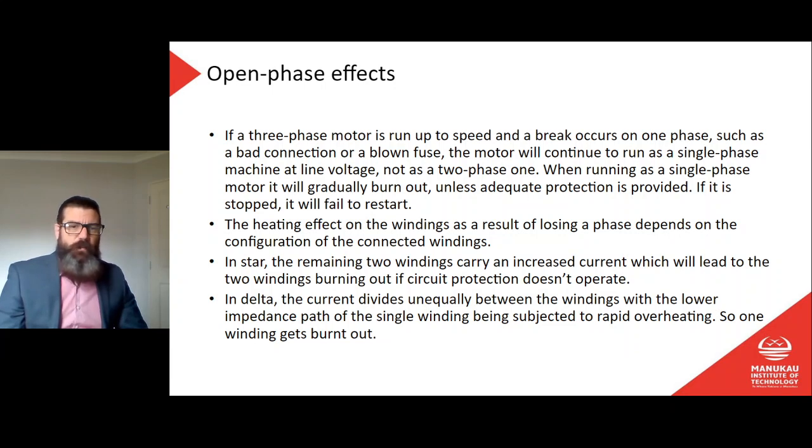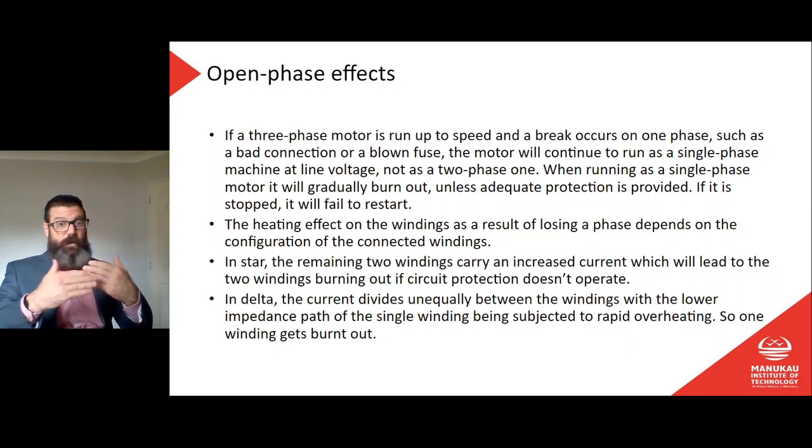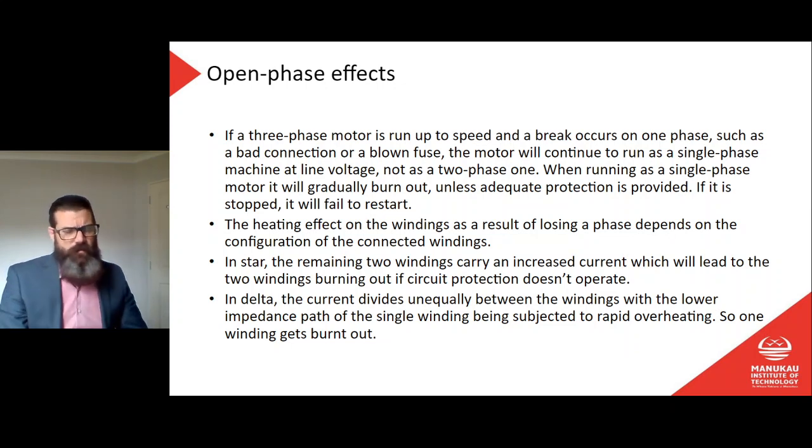The heating effect on the windings, so if it was stopped, it will fail to restart. It will continue running while it's running, and then when you stop it, it won't start again because now we've got that single phase effect, alternating voltage, and we don't have a starter on our three-phase motor, so it won't start.